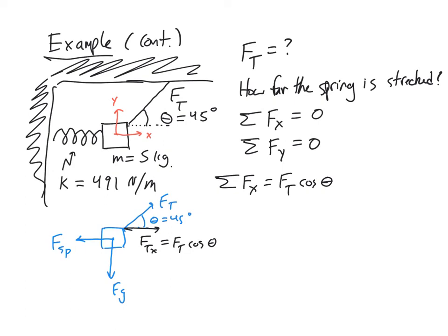And then we want the spring force. So we have to be very, very careful with the sign of the spring force. I'm going to write this as minus k times delta x. So I'm going to leave delta x as like unspecified sign. Now I expect delta x here is going to be positive because I've put the negative sign in there to indicate it's going backwards already. But I'm not going to make any guesses about it because I feel that might be a little bit dangerous and I might screw myself up. Those are the two forces in the x direction, so they sum to be 0.